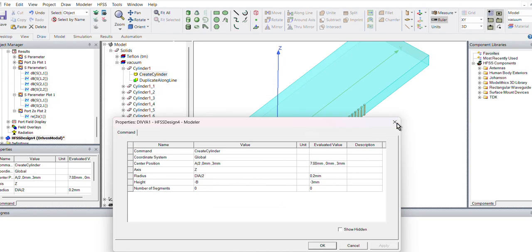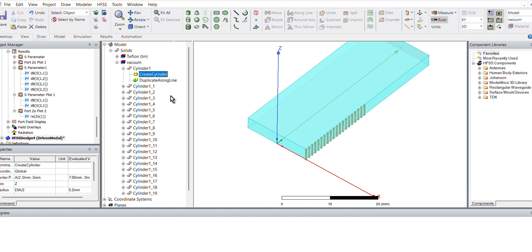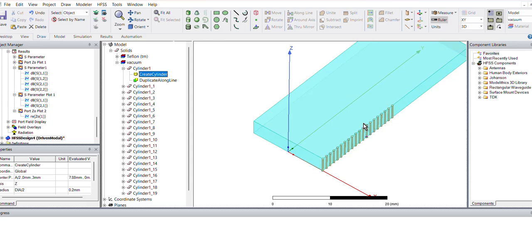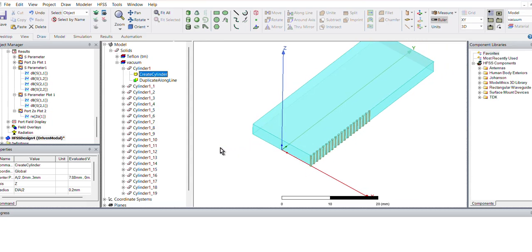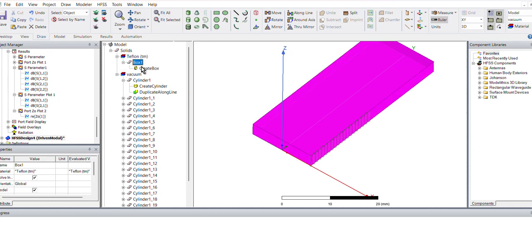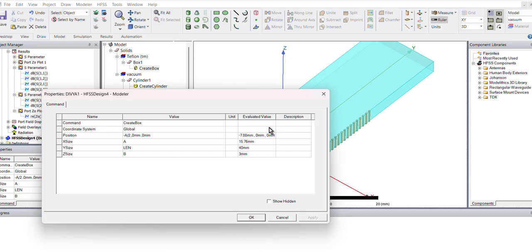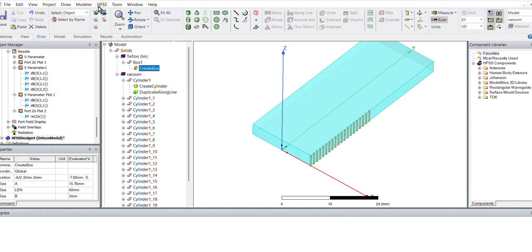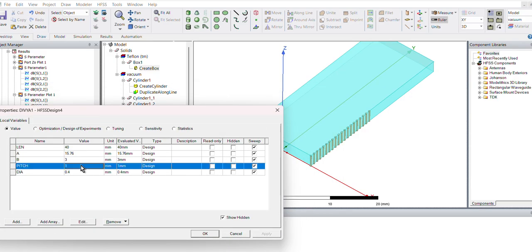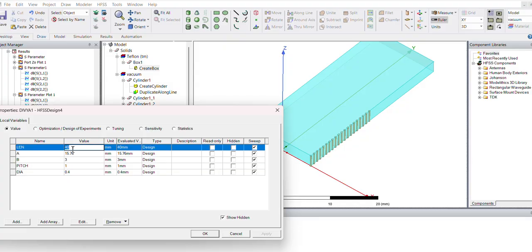And one more thing we shall do is that I want to do some simulations to see how the dimensions and everything affects my SIW. So what I shall do, instead of the old original block being whatever length it was, I shall define length as a function of pitch. So your length will be, because we are using 20 numbers, so 20 into your pitch.